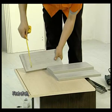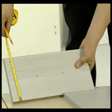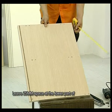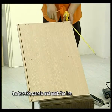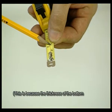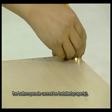First of all, measure the height of the door panels for each drawer with tape. Leave 25 mm space at the lower part of the two side panels and mark the line. This is because the thickness of the bottom panels for the drawer is 18 mm. If no space is saved, the bottom panels cannot be installed properly.